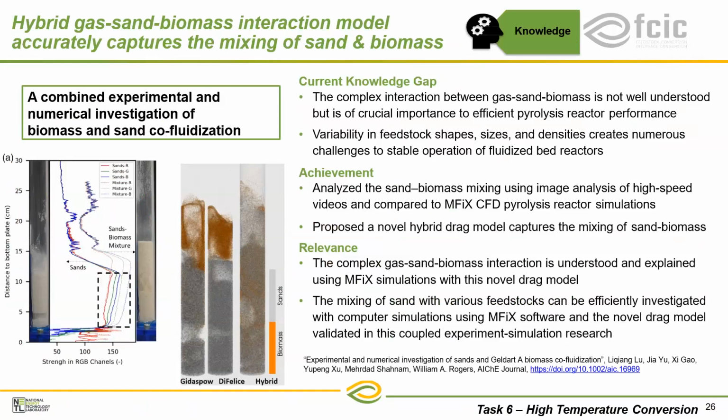So let's talk a little bit about those reactor scales. Now, pyrolysis of biomass is typically done in a fluidized bed reactor, an FBR, and sand is often used in that FBR as a heat exchange medium. But as you can imagine, biomass and sand have dramatically different thermal and mechanical properties, right? They're not the same thing. This contributes directly to the instabilities in those reactors, which can be catastrophic to the operation of the process.